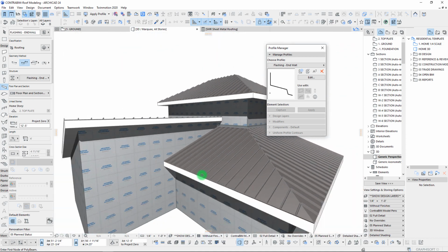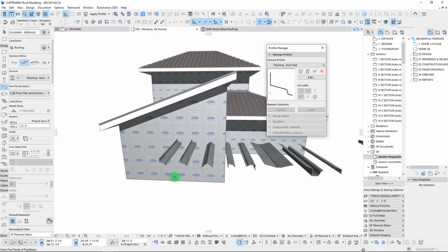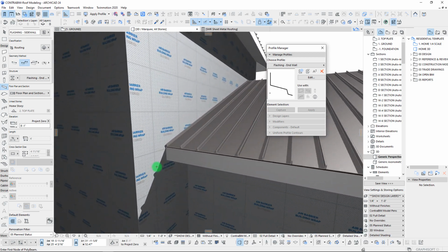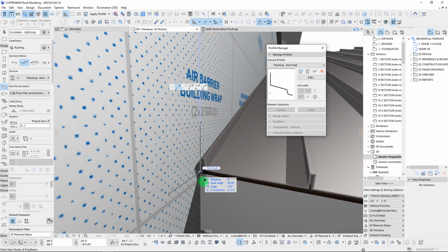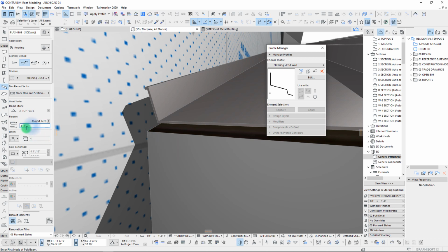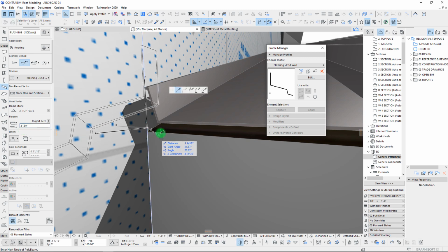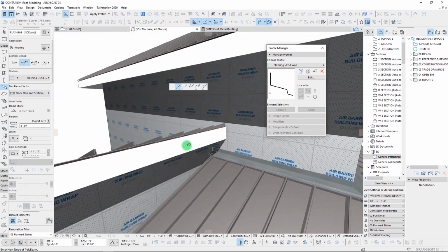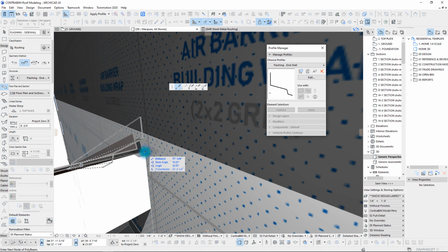So we'll turn off our finishes and let's work through our sidewall connection. I'm going to pick up the settings here. We can come over and start at this point here. We can see that we're a little bit higher than that working point. Once again, if we wanted to measure to get an idea of what exactly that is, we can see it's 8 foot 3/4 to our Z. So we can set that right here if we wanted. So 8 foot 3/4, and then we can simply click from here, and we'll snap it to right there.